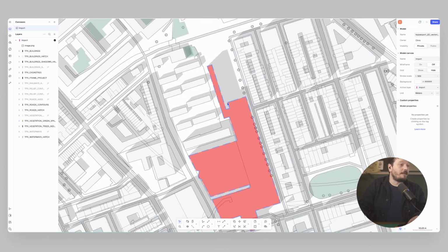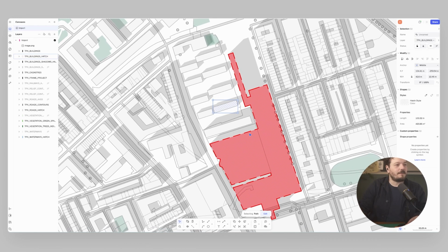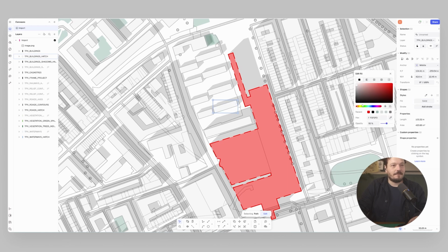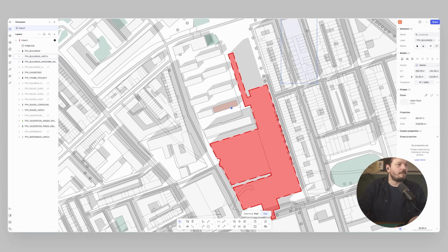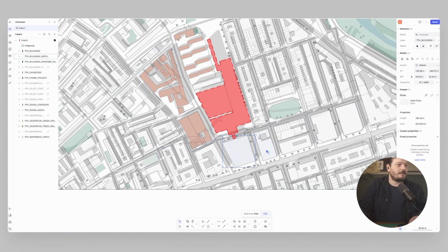And I could even go in and start pasting some of these buildings with a different tone, which highlights that they're within the building's vicinity or they have an impact, for example. So again, I could detach that tone and say maybe these have a more sort of orangey tone to them, like that, for example. And then I could save that as a style, so surrounding buildings. And then again, any of these buildings, I just need to use the picker style tool, and you can see there very quickly I can just go in and adjust them.